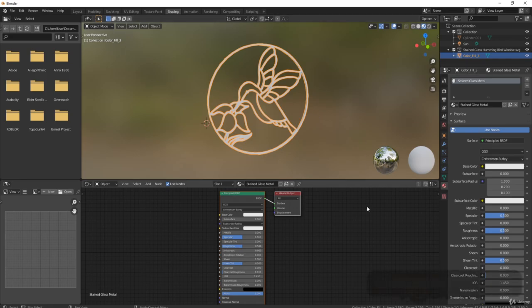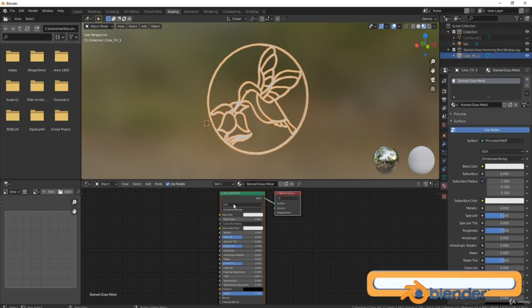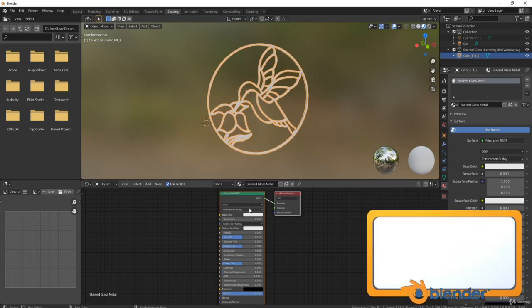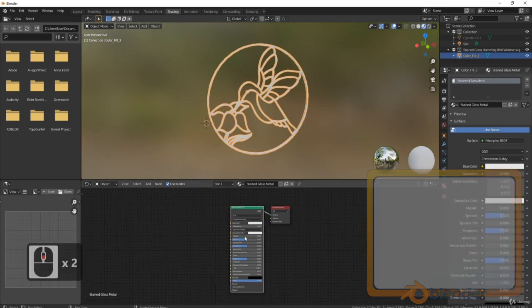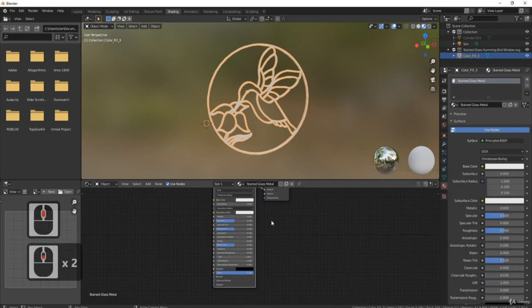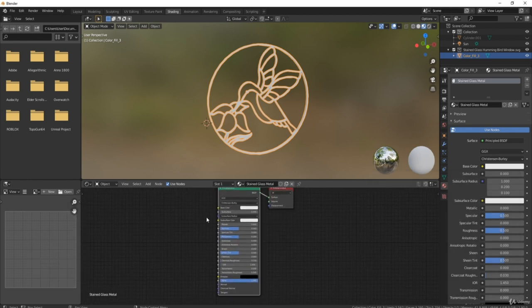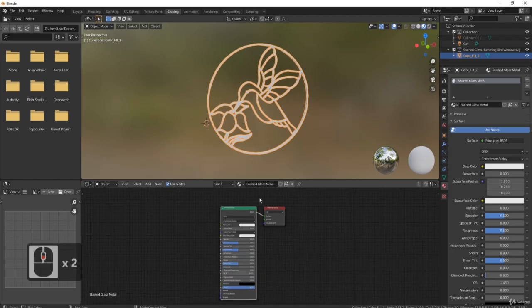Welcome back everyone to 3D modeling a Hobbit door scene with Blender 2.9 and Adobe Photoshop. So this is where we left it off, and you can see at the moment the standard material that comes in is called a principled BSDF. So every time you bring a material in, this is what Blender will try and bring in. And this basically is a super node. That's what I class it as, and I think that's what a lot of people call it, because you've got so many plugins to this. You can change the metallic, the roughness, everything is within this actual material node. So that is why it brings it in as standard, and that is why it's so useful.